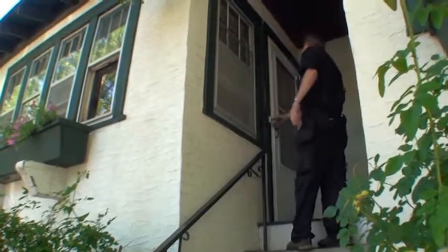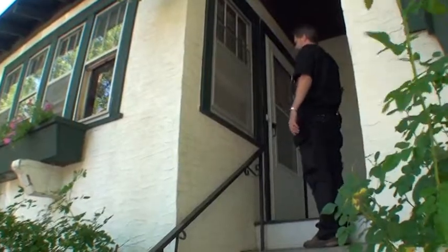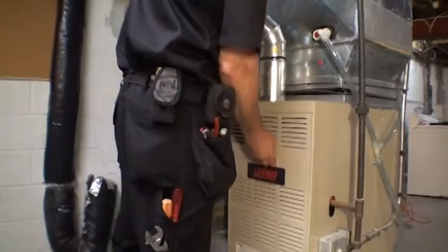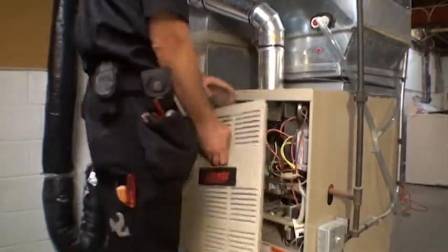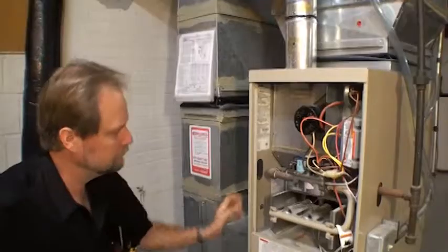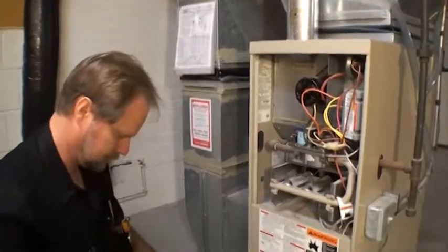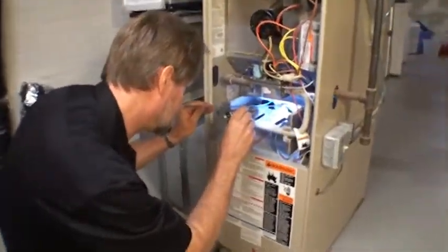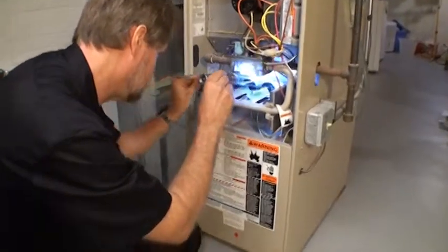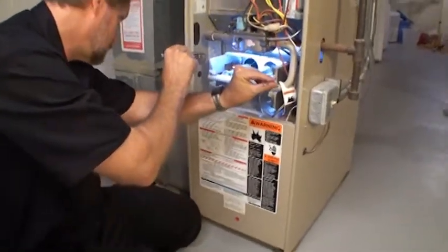When arriving at the client's house, introduce yourself to the client and hand them your business card. Be respectful to the client and explain what you are going to do. Start by removing both the furnace and the blower cabinet doors. Check visually for cracks in the heat exchanger. At no point during the clean and tune should you bang on the heat exchangers.